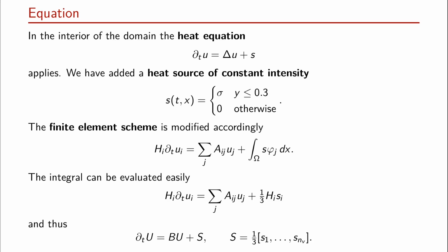And so we don't model all of the intricacies of the device, say the CPU that generates heat. We will just assume that it generates a certain amount of heat, and this we will plug into our simulation. And this we do by the source term here. And the source term in some sense is very simple.